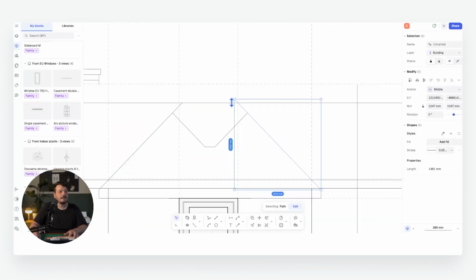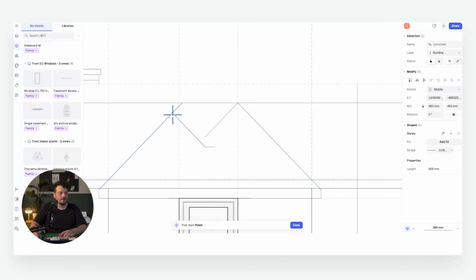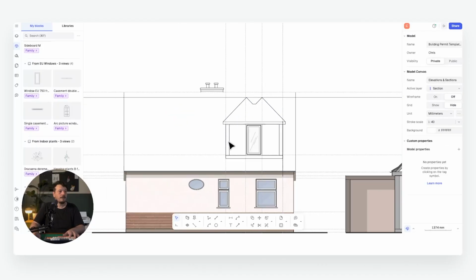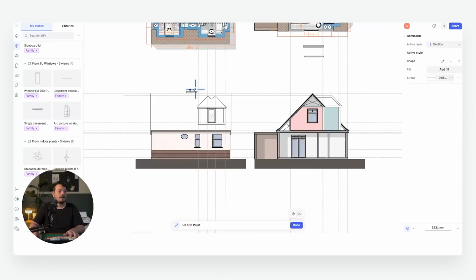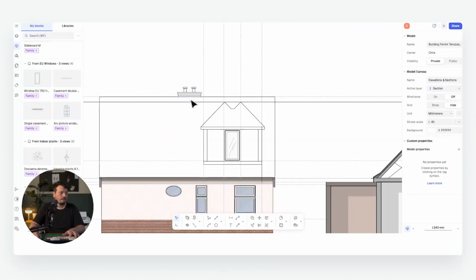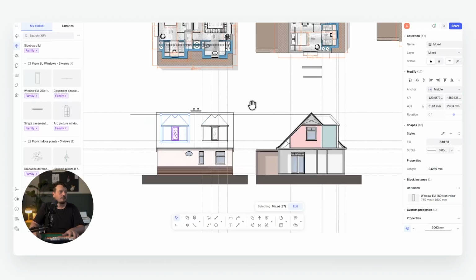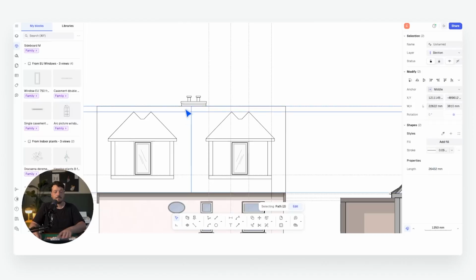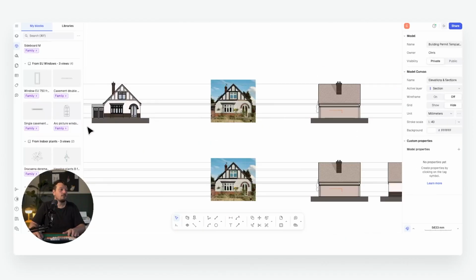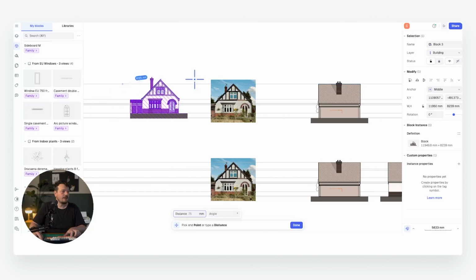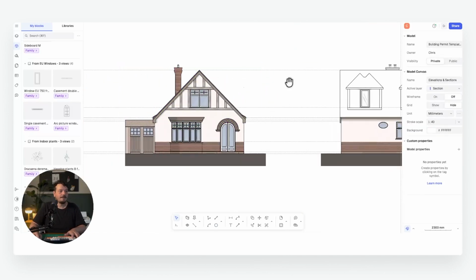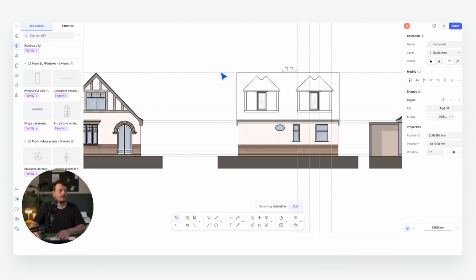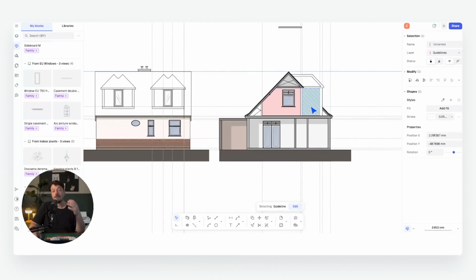And that's the thing, I'm kind of thinking in 3 dimensions, looking at the plan, looking at the section, and doing things as I go. Okay, and then I can find the center line of that roof, and then I can just mirror my dormer across. So then they sit perfectly and nice and symmetrically across the roof scape. And again, if I wanted to then transfer that across to the front elevation, I can then read that in conjunction with the lines that I've set up, but I can also create another view looking back at that section.